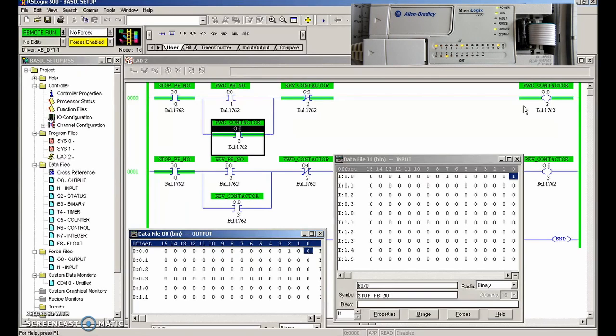But you can see that the PLC is still trying to turn it on. So if I reset that overload, then it pulls right in. I don't want that. I don't want the motor to turn right back on after an overload state. So that's a little bit dangerous, having the contactor turn on. Again, here's an overload, kicks out my contactor, you can hear that. But the PLC is still trying to turn it on. I don't want that at all. I need to have another instruction here for the overload to send a signal into the PLC to turn that off. Essentially, it's going to act as the stop push button and turn it off.